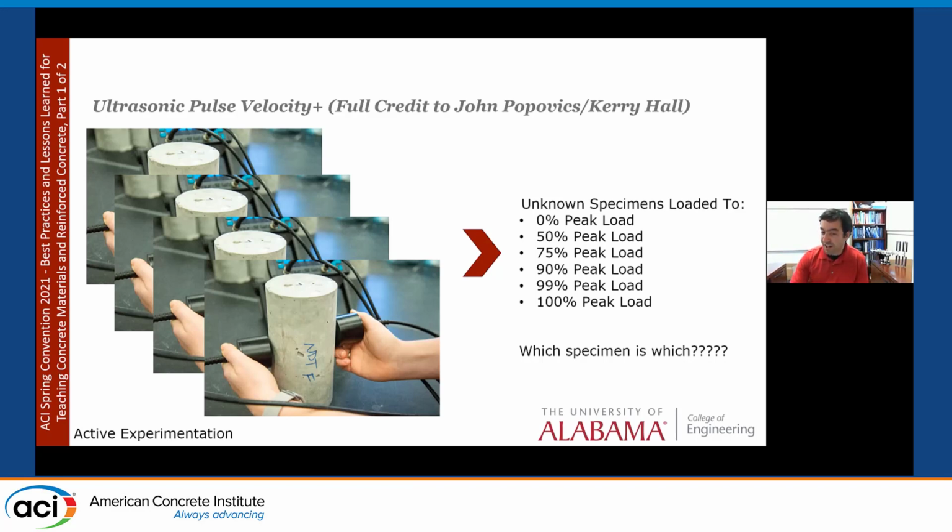But that's why you're there helping them kind of think about how they're going to take the classroom and actively do this activity. Now, and I'll mention this in the lessons learned, the photo shown here is on 4x8 cylinders. That's a horrible size, as I discovered. If Chris wants to ask a question, what would I not do again? I would never use a 4x8 cylinder. It was awful, you could barely distinguish anything. 6 by 12 is the way to go. But we'll get to that in the lessons learned.